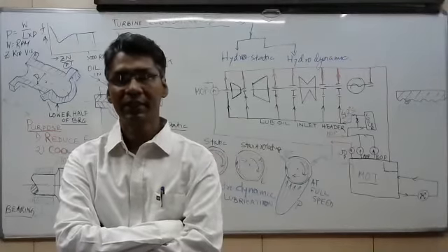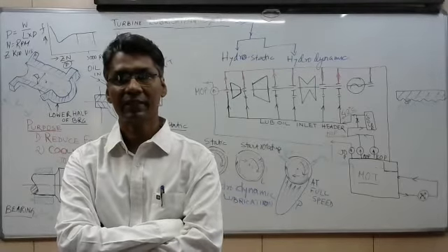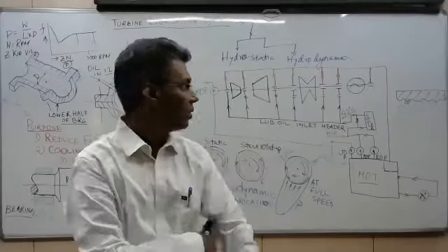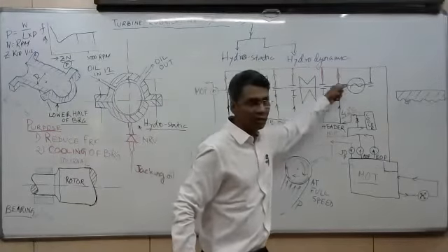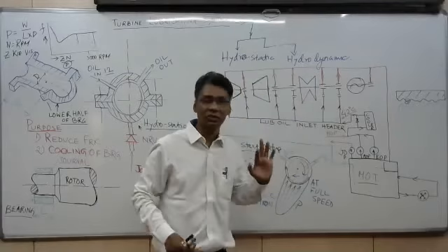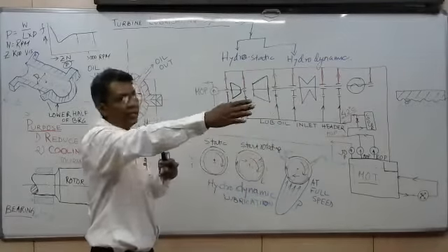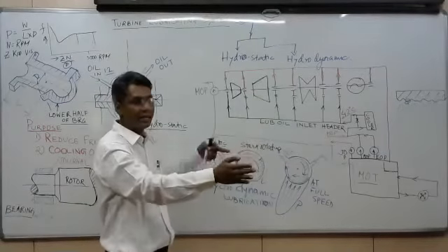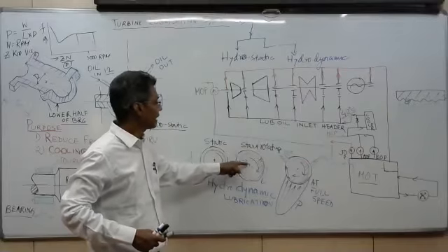Sir, at starting it seems that the rotor and bearing are eccentric. Will it disturb the system? So this is a single shaft. All the generators are on a single shaft, that is called tandem compounded. If it is shifted to the right side, every bearing will be shifted to the right side, not just a single one. So there is no question of eccentricity.